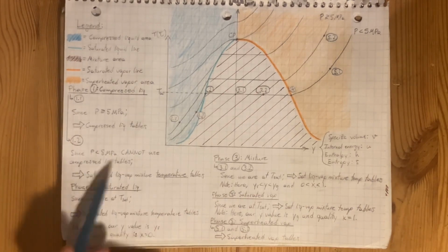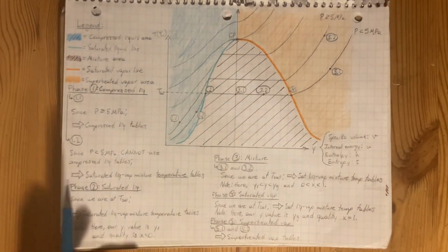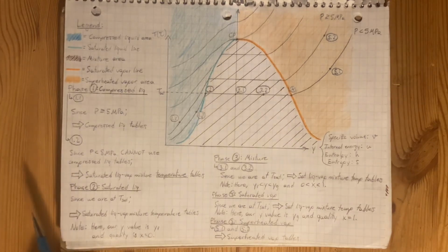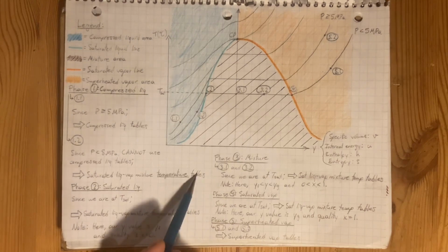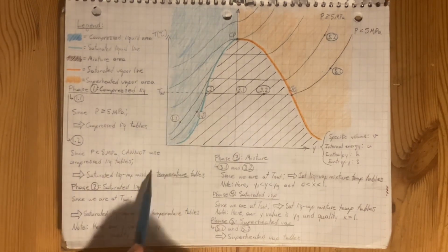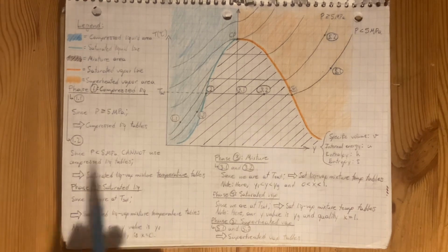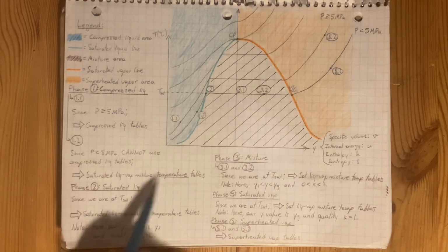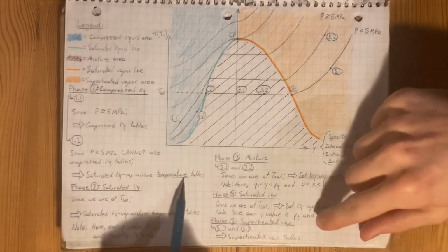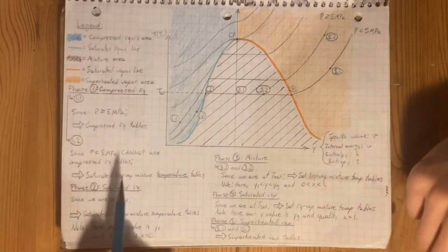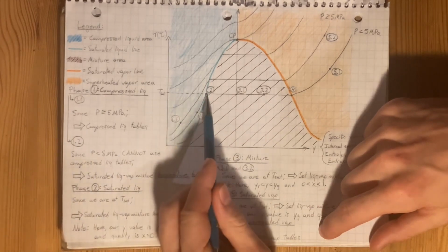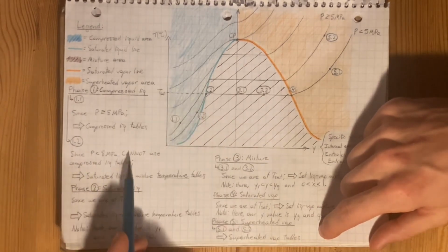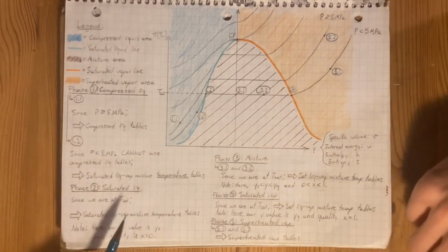If, however, it is lower than 5 MPa, the behavior of the substance is actually not really adequate if you look at the compressed liquid tables. So you're going to have to use the mixture tables, but not any mixture table. You actually have to use the temperature table because the assumption does not work on the pressure table. Basically you would just assume your temperature, or pressure, to be the saturated pressure or temperature, so to be this pressure here. That is when the pressure is lower than 5 megapascals.